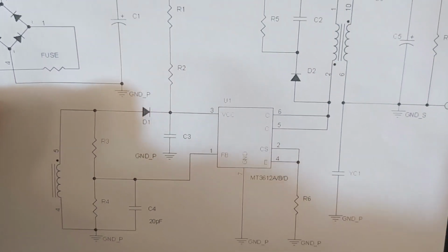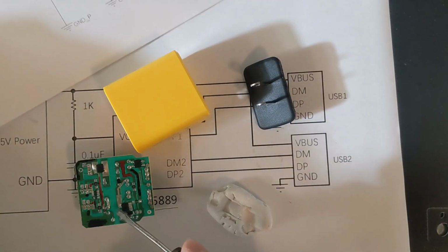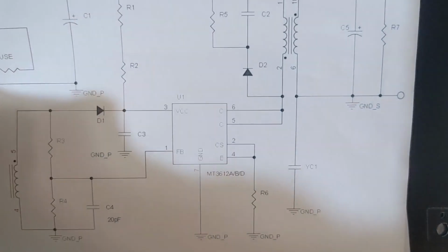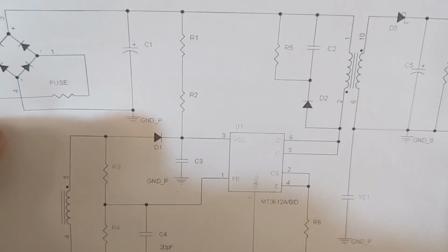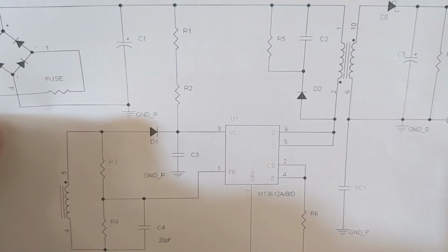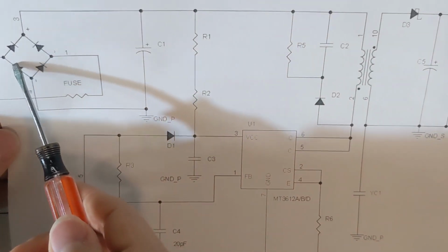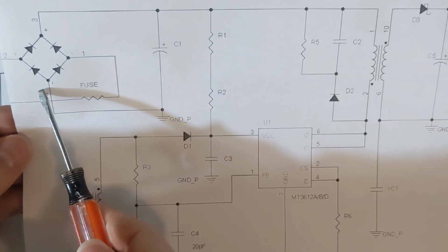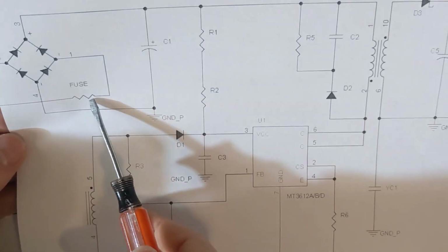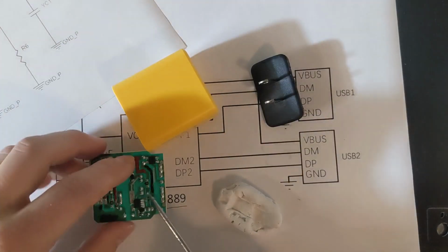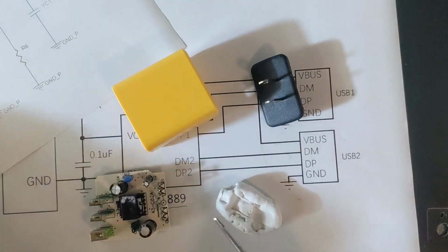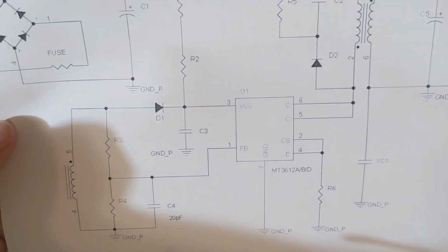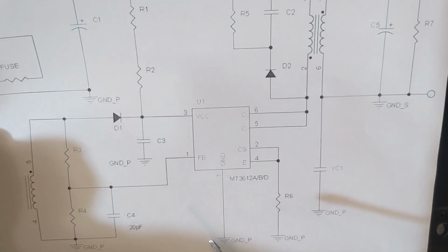So right here is the schematic for that chip, the chip that's right here. And the interesting thing is, this is all supposed to be very inexpensive so that they can sell lots of these and make money on them, obviously. But you basically have your input power, 120 volts in here. And then you have a fuse. Now, they didn't really put a fuse, but they did put this resistor here. So I'm assuming that that's kind of a custom-made fuse or serves the purpose of it. And then you have the chip.